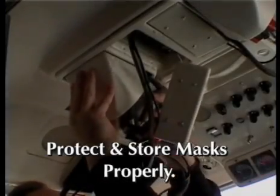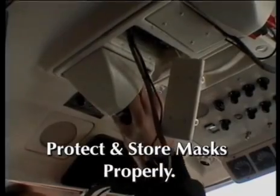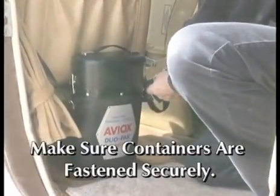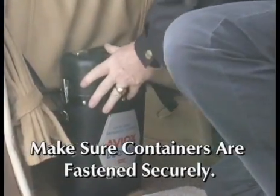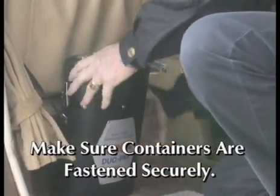Protect your oxygen mask from direct sunlight and excess dust. Store masks properly. Inspect your portable oxygen storage containers to make sure that they are securely fastened in the aircraft. Turbulence or abrupt changes in aircraft attitude can cause them to come loose.